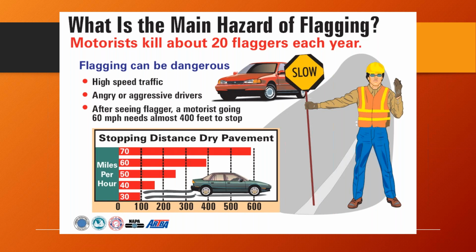So it's one of the reasons why the advanced warning area is so important, so that we don't surprise motorists as they're approaching our flagging operations, so they begin to slow down even before they see us.